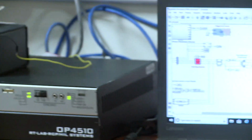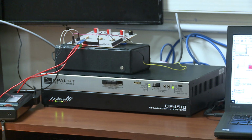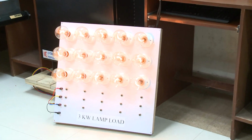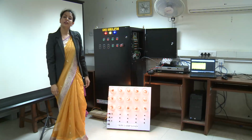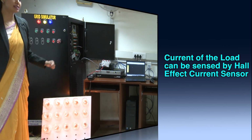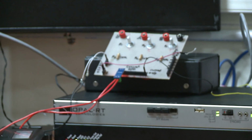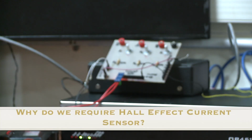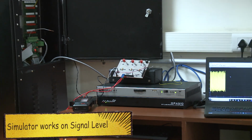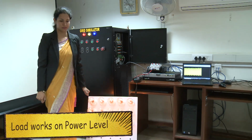This model is then tested on a real-time simulator OP4510 and through the grid simulator, it is connected to a 3 kilowatt lamp load. We are also sensing the current signals from our load via the Hall effect sensors and feeding them back to the real-time simulator through the analog in. Now, why do we require these Hall effect current sensors? This is because the simulator is working in signal level, however, the load is in the power level.